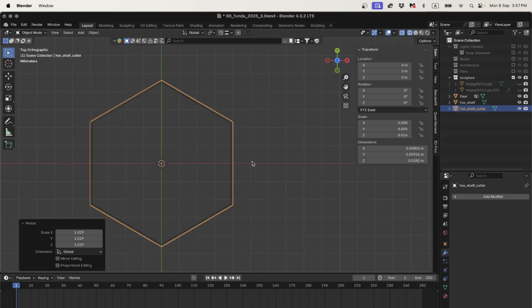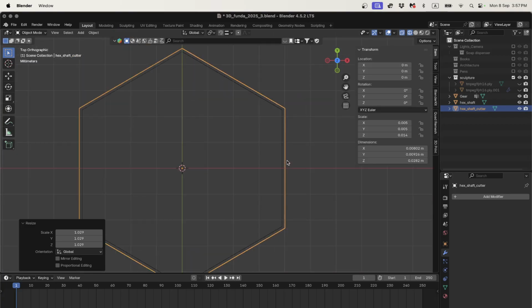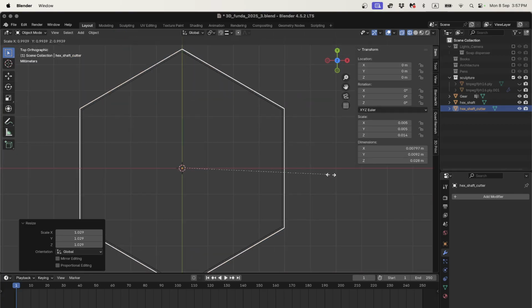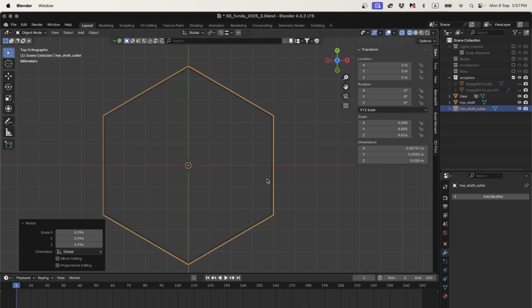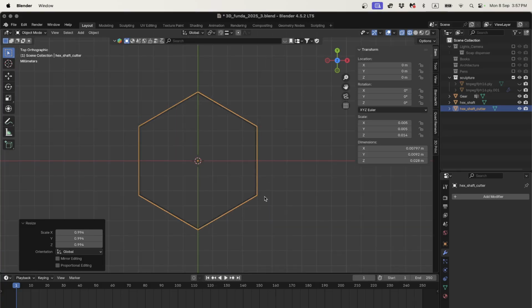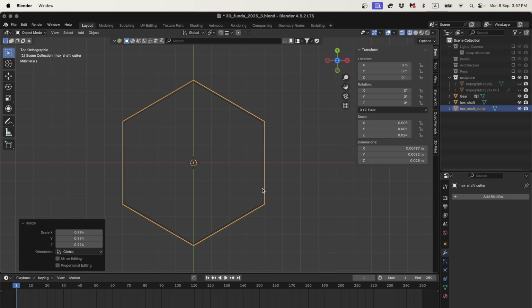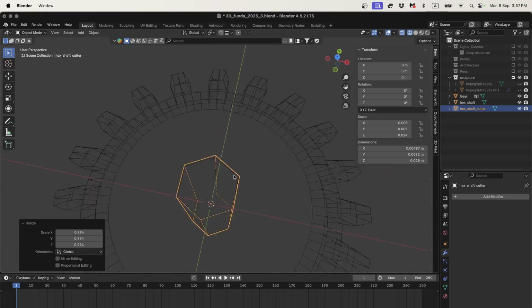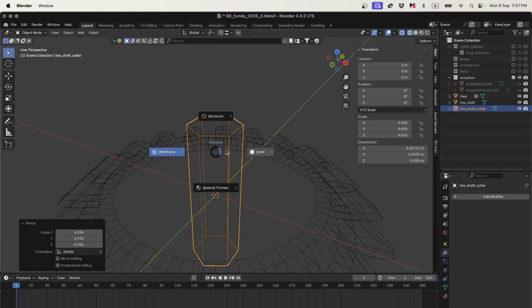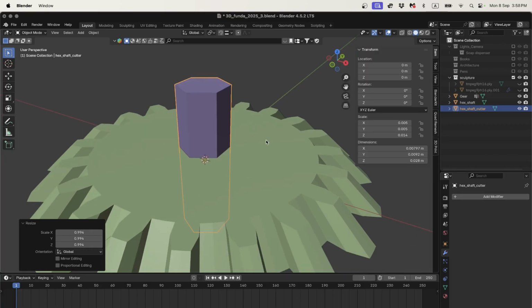We could measure this, usually we might leave a fraction of a millimeter. I'm just going to eyeball this, and then I'm going to print it and test it, because every 3D printer can be a little bit different depending on its accuracy, so I'm kind of hoping here more than knowing. And if this all works, we might make some notes in our course document of what exactly that gap should be. Okay, but let's go back to solid mode, and now I'm going to use this cutter to put a hole in the gear.